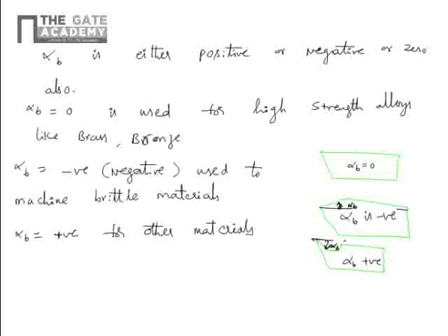Heat conduction: tools with large rake angle do not conduct heat readily, whereas tools with negative rake angles have better heat conductivity, because the surface area of contact is more, so heat transfer will be more.